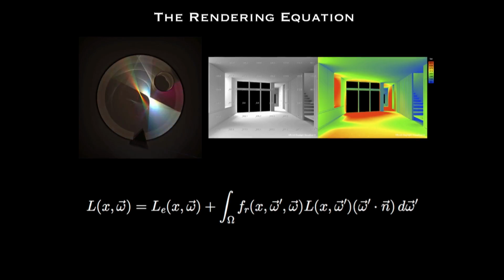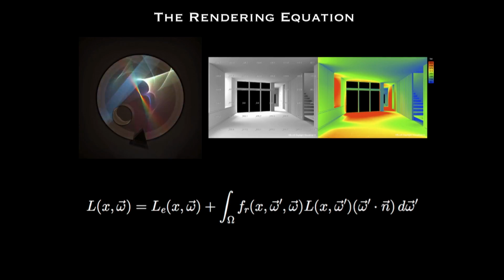So we started thinking about it, and on my research side, I was fortunate to work with some really smart people. And we looked at this equation. This equation is actually shared between the Daylight Visualizer and actually all software that computes lighting solves this equation. I'm not going to talk about it for a long time, just say what it describes is light at a point is equal to the light that's emitted at a point plus light reflected from all other points in the scene. Relatively simple, but complex to compute.